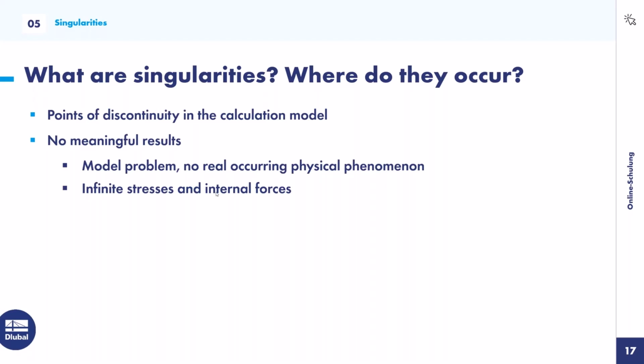And the further you go away from this central point, the more the stresses decrease. Also a problem, the mesh refinement does not improve the result. It's the other way around. A mesh refinement will most likely be more harmful to the result, since the nearer you come to the point, the higher the result gets.